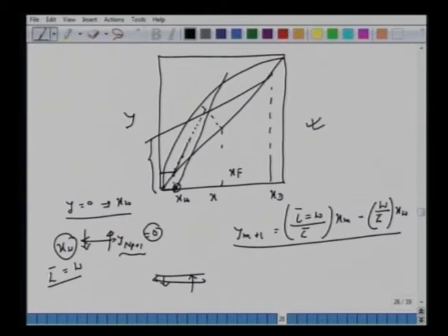Alright. Now again, you should go back and carefully see that this open steam system, whatever we're calling it here, is nothing new. New in the sense that our approach remains the same. You write down the operating balance equations or species balance equation for this bottom envelope, the section underneath the feed, to realize that there is a modification in the overall material balance and a modification in the species balance for this stripping section here. And then the modification comes from the realization that we don't have a reboiler.